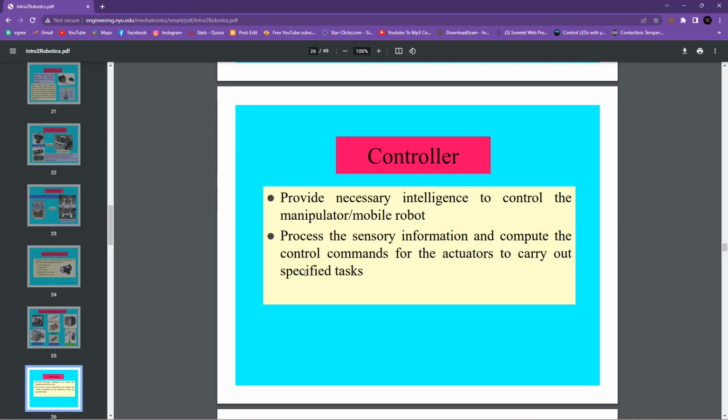So how does this work? The hand sanitizer is programmed in a way that when the information received from the sensor meets a particular condition, then the actuators should perform a specific task. For instance, if the ultrasonic sensor senses a distance less than or equal to 10, then the actuator, the motor, should rotate for the sanitizer to come out. The same applies to automatic dustbins.